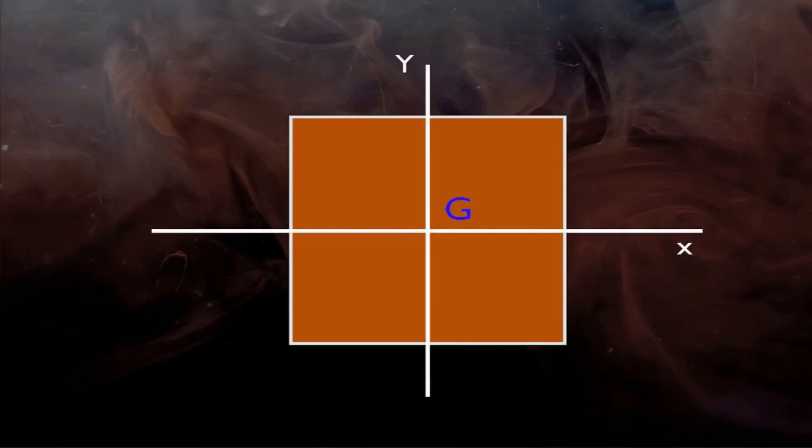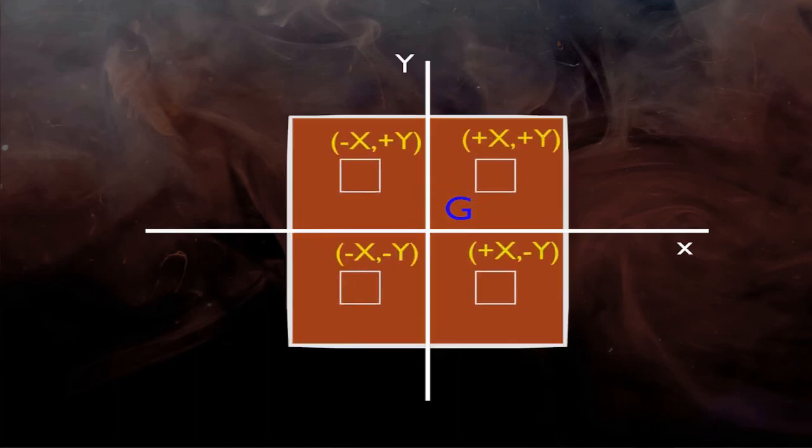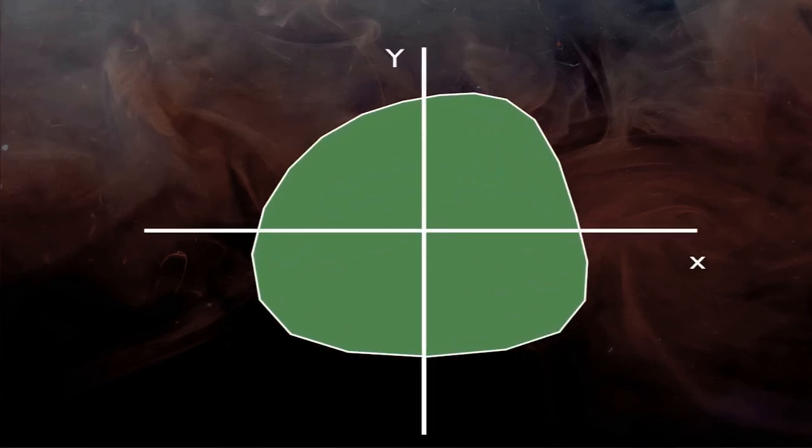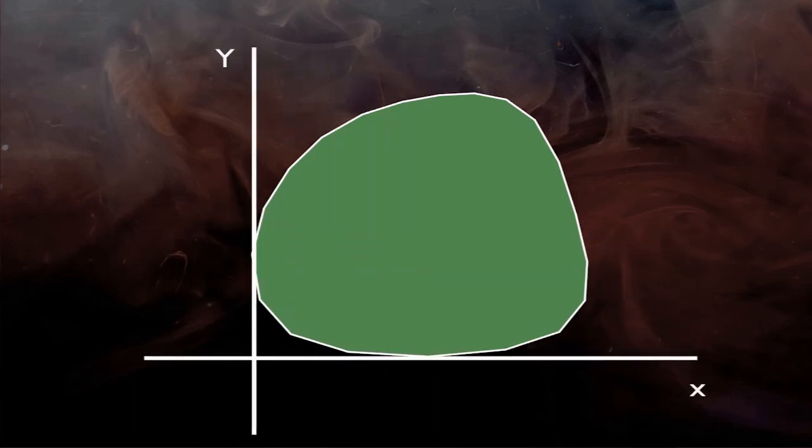For example, for symmetrical shapes, if we place the reference axis in the middle, the centroid location will be the center of the reference axis, as there will be a similar element of area dA available in all opposite directions to nullify the effect. But for irregular shapes, it will be tedious to calculate all positive and negative values. So generally, the leftmost and bottommost planes are considered as reference axes.